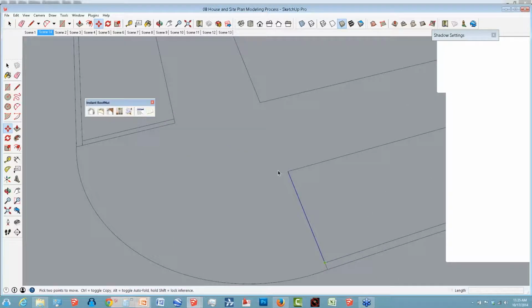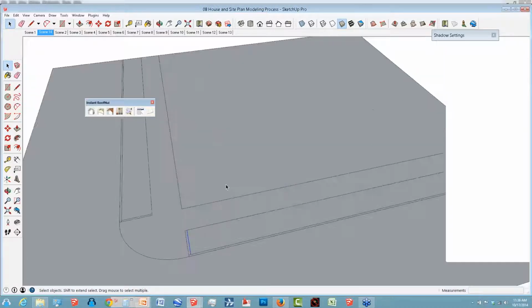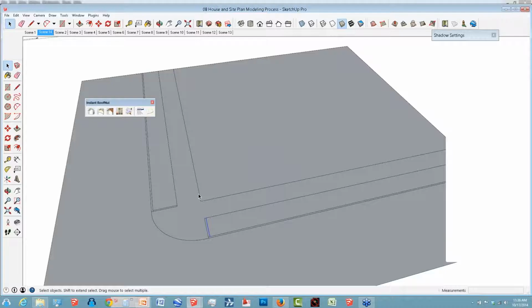And we're going to keep going. Next, I'm going to add a perimeter wall to this whole thing. I showed you how to use the offset tool to select edges. The beautiful thing about the offset tool in SketchUp is it lets you offset surfaces. The tools I'm using primarily for what we're doing here are the rectangle tool, move tool, push pull, and offset. Really, that's all you're doing to model this basic site plan.